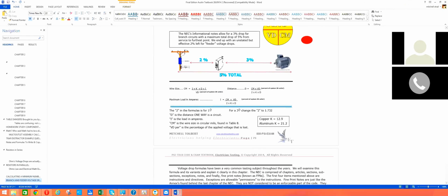All right, so I'm looking at this percentage, and on this branch circuit, which is maximum 3%, I've got a total distance of physical separation between the two, but I also have the total length of conductor, which is one wire going to the motor and one wire coming back from the motor. I have to have a complete loop or closed circle for my electricity to flow. With a single phase motor, I'm going to use the line side and the load side, the neutral or grounded conductor, which is the proper term for it. I'm going to use those two wires with the same load current values. It's one wire there and one wire back, or if it's a single phase 208 volt, I'd have a black and a red, so two line values going out there, but I'd have one wire going and one wire coming back either way.